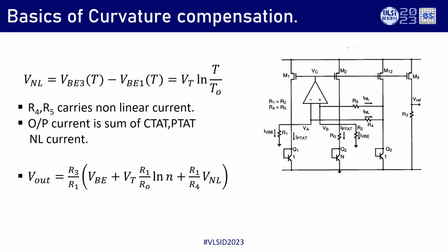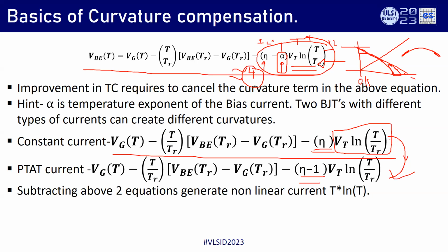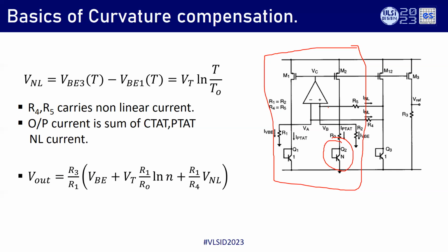So what he had done is, this is the traditional current mode bandgap, right? Already these BJTs are getting the PTAT current, so that means this expression is solid. Now how to generate this, because it needs constant current? One advantage of the Banba bandgap is the constant current is available in this leg. So why can't we use that leg to bias another tiny transistor? Now, this voltage is equation 2 in the previous slide. This node is equation 1 in the previous slide.